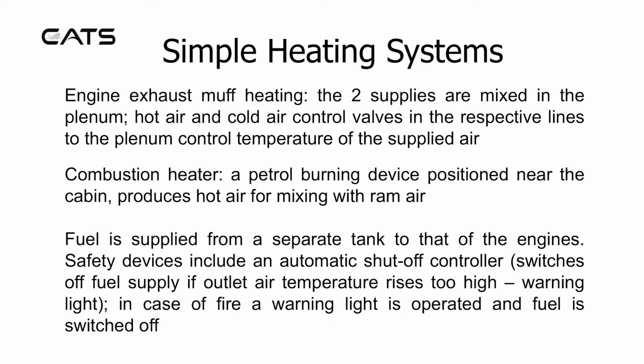Fuel is supplied from a separate tank to that of the engines. Safety devices include an automatic shut-off control valve, which switches off the fuel supply if the outlet air temperature rises too high, and provides a warning light. In the case of a fire, a warning light is operated and fuel is switched off.